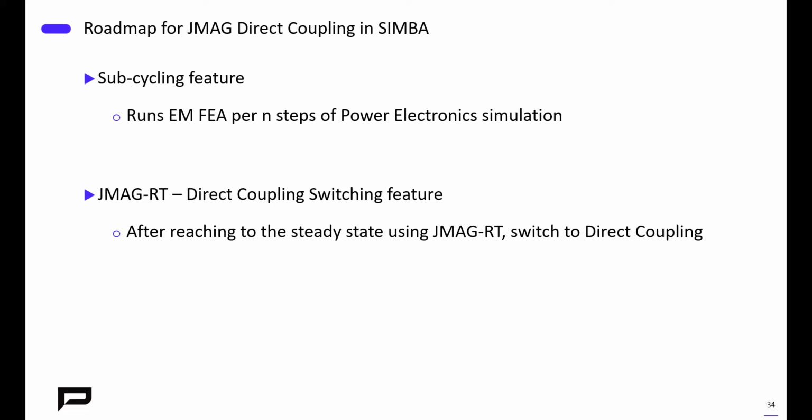Yeah, maybe I can answer that. This is Emmanuel from the SIMBA team. So actually what you can do in this type of simulation is you can extract the profile of the junction temperature of the semiconductors, because we can model the actual thermal impedance between the junction, the case, and whatever coolant or cooling system you have.